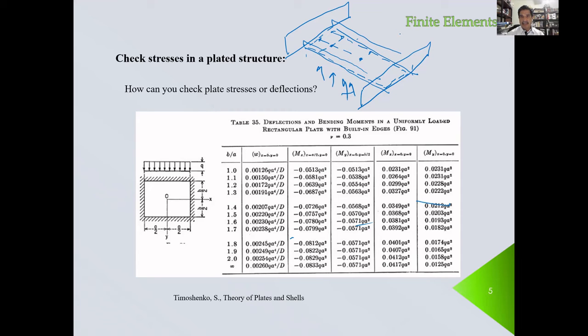And we can consider that this plate is a rectangular plate clamped on all edges. You can say, wait a minute, but the edges are not clamped. I know. You can say that the pressure is not uniform. You can take an average. But the thing is that you have to check the order of the response.